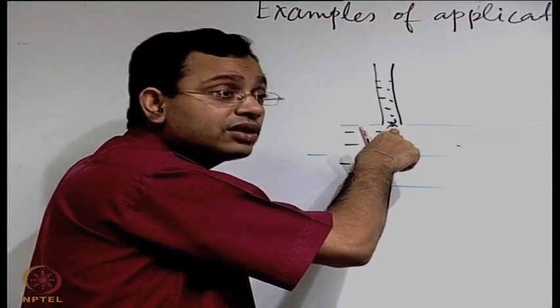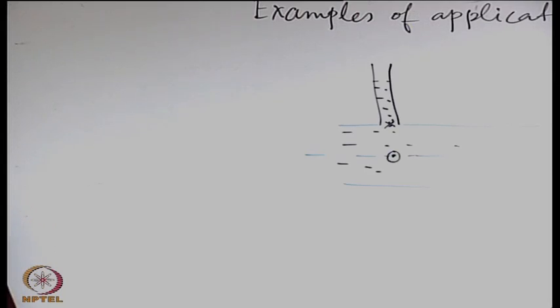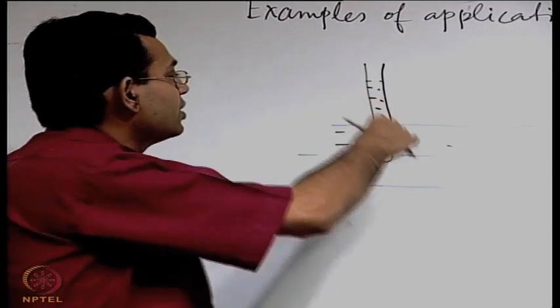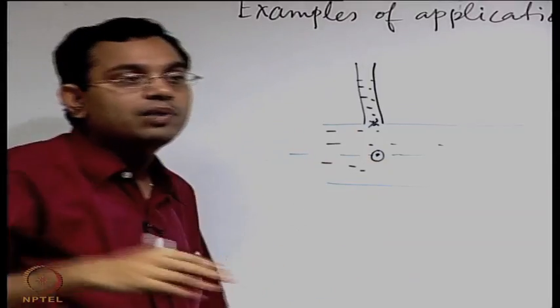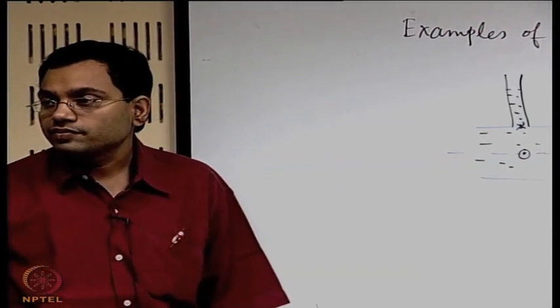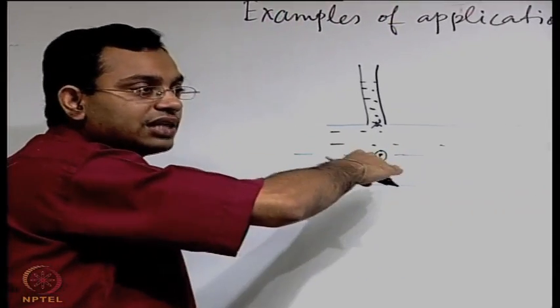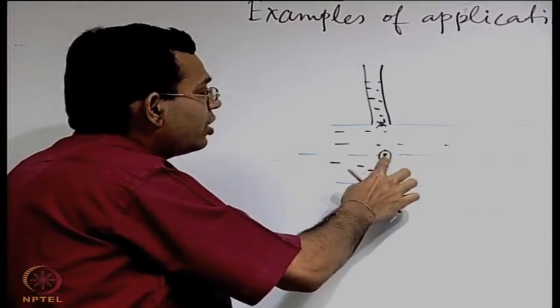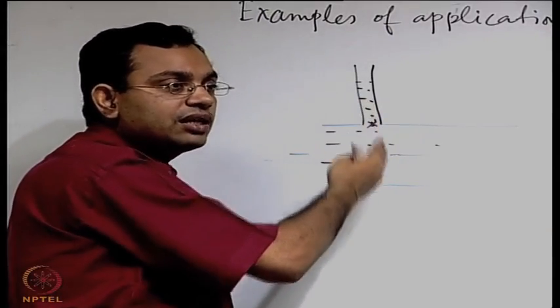When you have a curvature of the streamline. We have just in the previous lecture seen that you have a gradient of pressure in the direction of n only when the streamlines have a radius of curvature which is non-infinity. But here, if we consider that the streamlines are parallel to each other, then you do not have that effect of streamline curvature in terms of the pressure gradient.